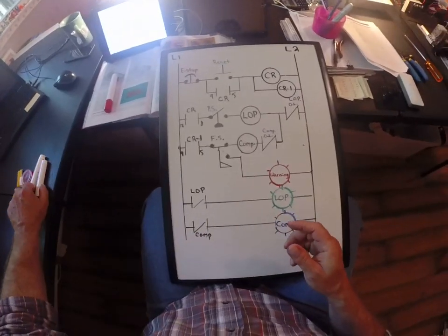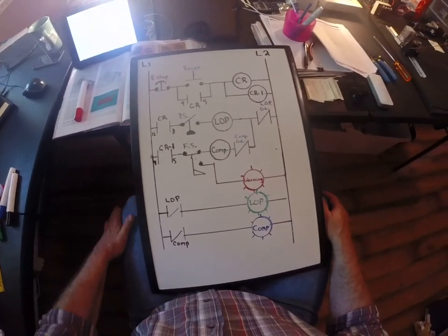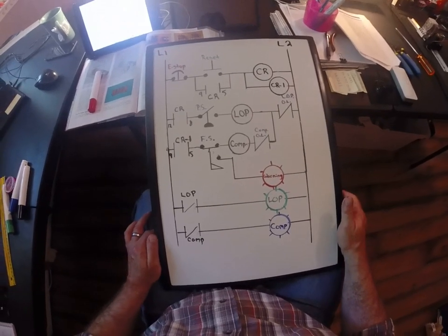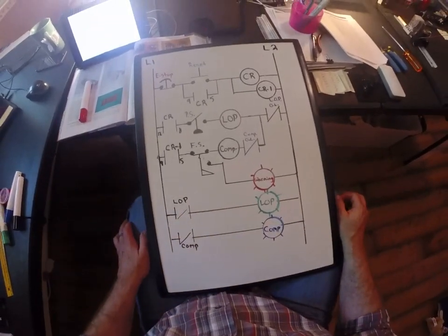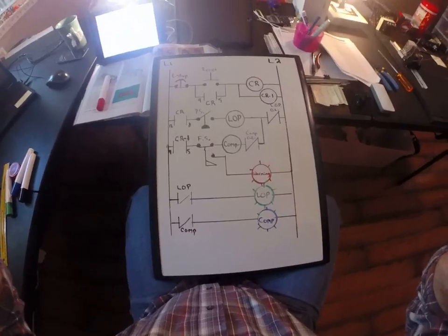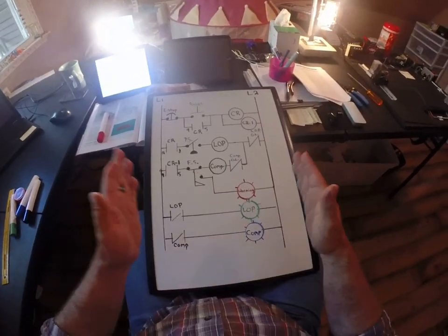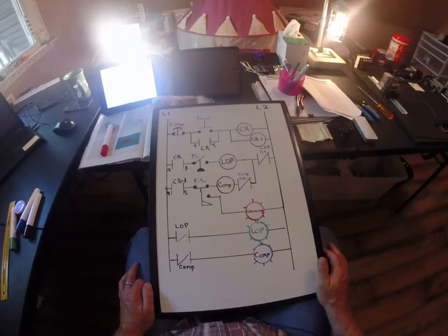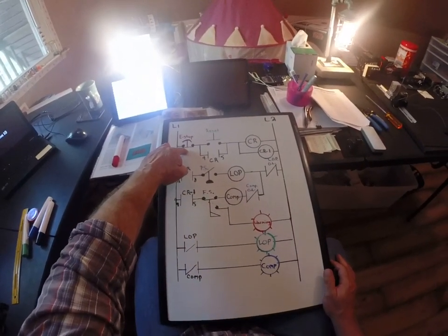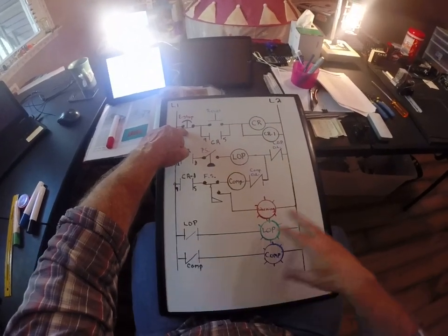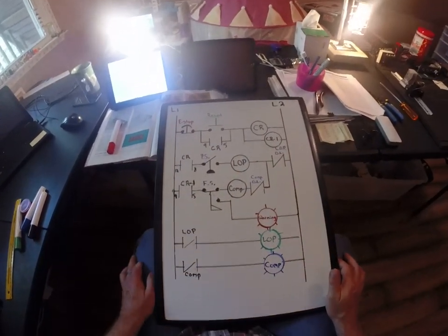You remember the sequence, we wrote it down last week when we were messing around with this circuit, and this is how we can add to it and make it a little bit better for the purpose of our lab. So, a simple way of just being able to add to a circuit. We will add more to this. We're going to add another button, and we're going to turn all this into 120, and we're going to have a 24 volt start to get this going.